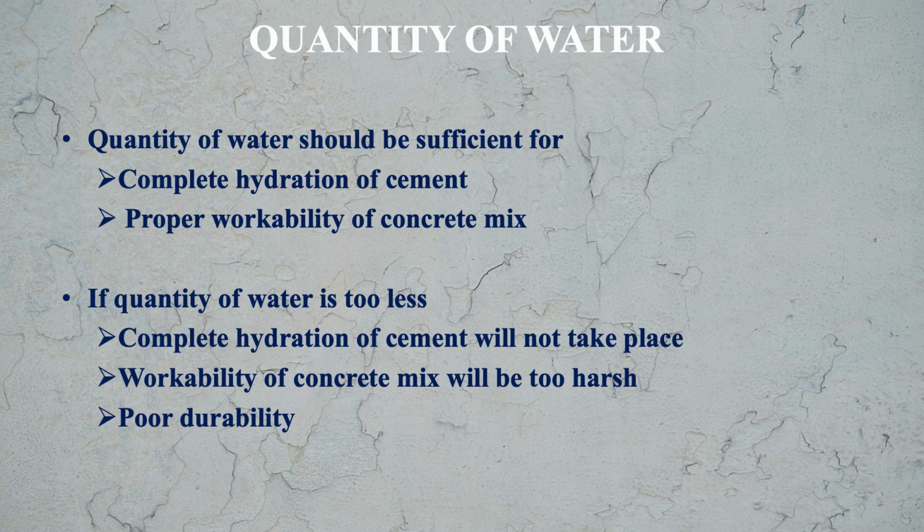Now if quantity of water is too less, then what may happen? Complete hydration of cement will not take place because a certain amount of water is required for hydration of cement. So if that particular quantity of water is not available, then complete hydration of cement will not be there.